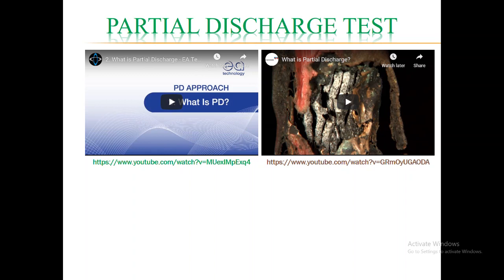Localized discharge means discharges which occur partially. The discharge does not bridge the gap between the two electrodes, but occurs locally. These imperfections, being small, are not revealed in capacitance measurement, but were revealed as a power loss component contributing to an increase in the dissipation factor. In modern terminology, these are designated as partial discharges, which in course of time reduce the dielectric strength or electrical strength of an insulation and lead to a total or partial failure of the insulation.